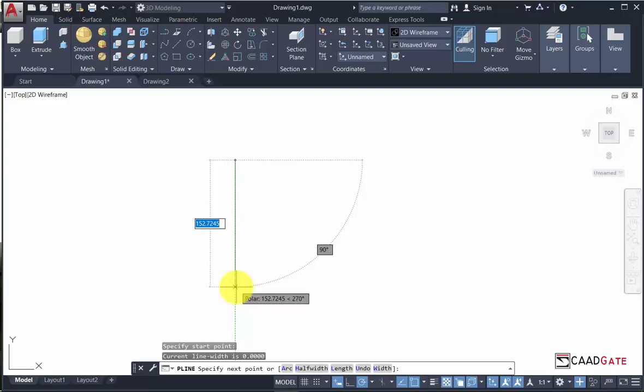So you should consider getting an external mouse if you don't have one already. A 1-inch angle bar is 25.4 millimeters, and for the purpose of this training, except otherwise stated, all our measurements will be in millimeters. I'll go ahead now and enter 25.4 and hit enter.